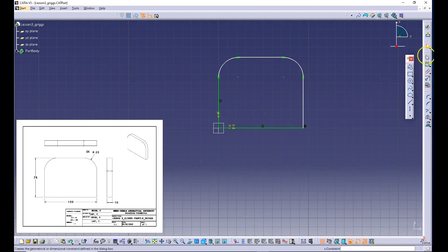So over here on the constraints toolbar that looks like this, I've got length constraints underneath our typical constraint tool. I'm going to click on that. I'm going to click on the line segment that I want to populate, and I'm going to place my measurement. So at this point you should be going, okay, 3.712, maybe not the right number that I want. But more importantly, is it inches? Is it units? Is it feet?